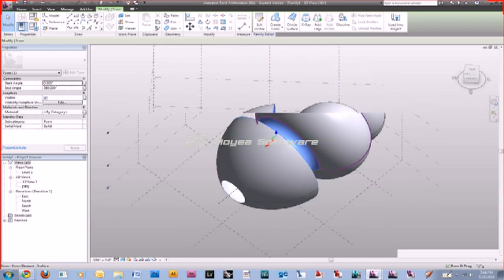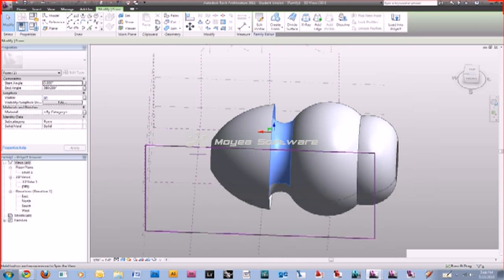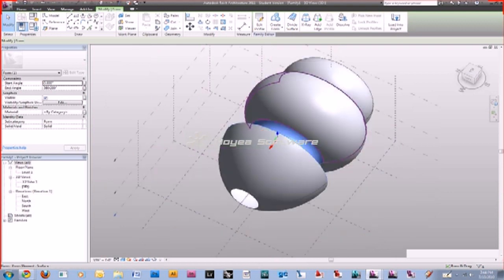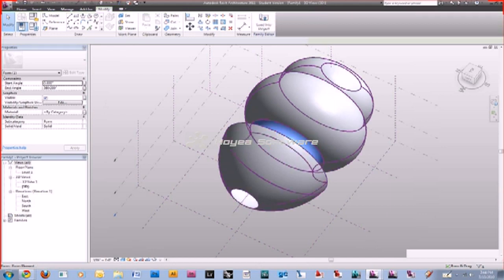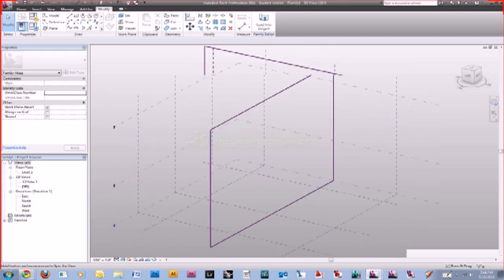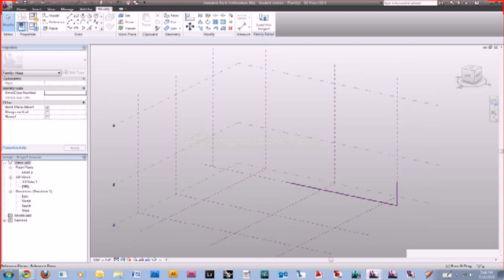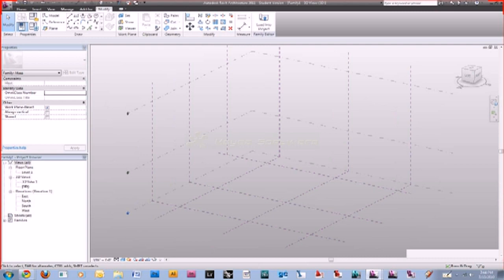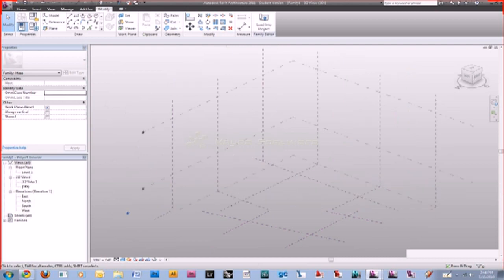Alright, so that's revolve. All of them are created the same though. That's just what we're going to call it. And then the last one is sweep, which is probably one of the cooler ones, I would say, because besides loft, you'll figure out that loft can be pretty amazing. You can create a whole skin of a skyscraper out of just the loft tool. And so it takes weeks and turns it into a day. The sweep tool, though, you can really create some custom stuff with sweeps. For anything, for the family components in Revit, for the in-place masses, or a conceptual mass.